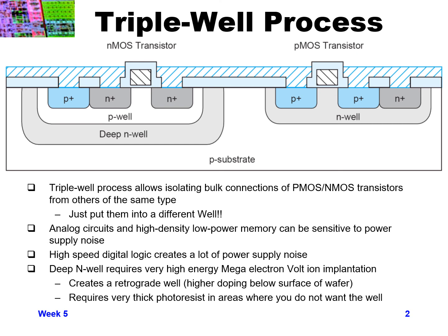And this typically might even be done before the normal N well. So we diffuse a really deep N well, and this deep N well basically acts as a barrier region, if you want to call it that, between the P substrate and the P well. If we were doing, let's say, a dual well process, we would just do an N well and a P well. But if we did dual well, the P well would be shorted to the P substrate. By doing this deep N well before we do the P well, we get basically a barrier region between the P substrate and the P well.